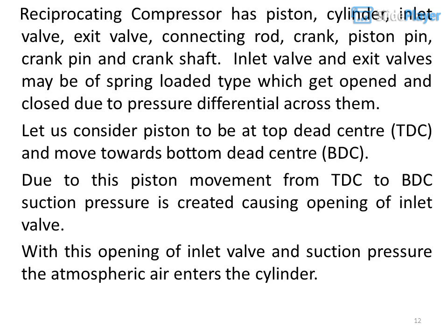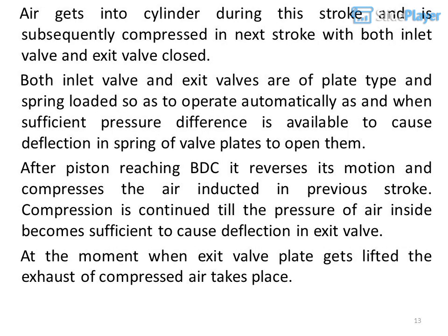Due to this piston movement from TDC to BDC, suction pressure is created, causing opening of the inlet valve. With the opening of the inlet valve and suction pressure, atmospheric air enters the cylinder. Air gets into the cylinder during this stroke and is subsequently compressed in the next stroke with both inlet valve and exit valve closed. Both valves are of plate type and spring-loaded so as to operate automatically as and when sufficient pressure difference is available to cause deflection in the spring of the valve plates to open them.